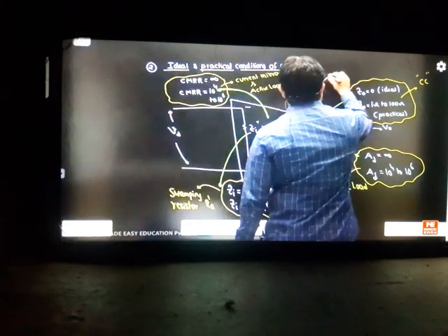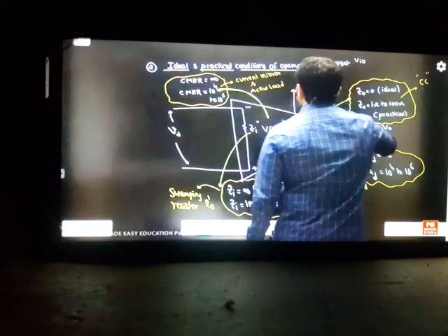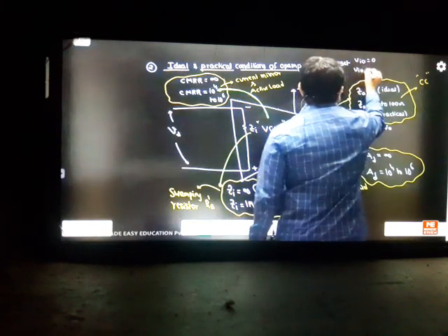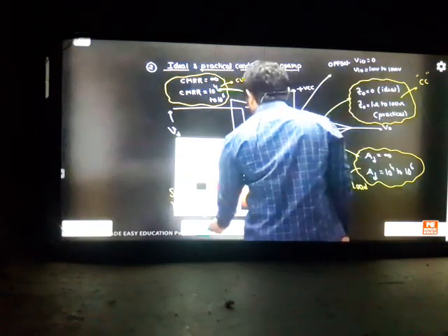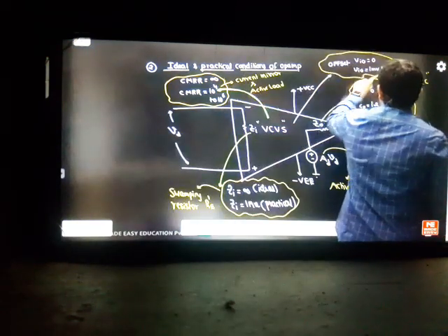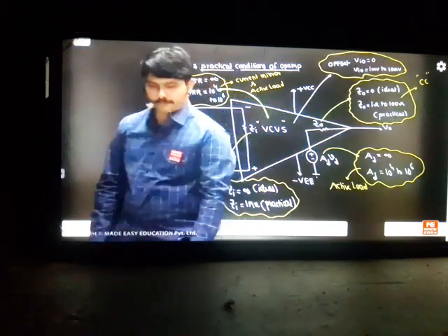Offset means VIO, the input offset. The output should be 0 as expected, but we are getting an offset of around 1 millivolt to 10 millivolts of input generated in the op amps. So an unwanted input is coming, this much. Actually the unwanted input should be 0, but it is maintaining some millivolts of input. That may create disturbance to your amplifier outputs in the coming classes.